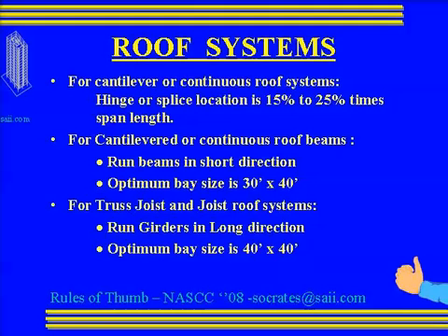On the other hand, if you're using joist and truss joist systems, you run the girders in the long direction, and the optimum bay is 40 by 40, which of course has no long and short, but if you ended up with anything else, is that still correct?